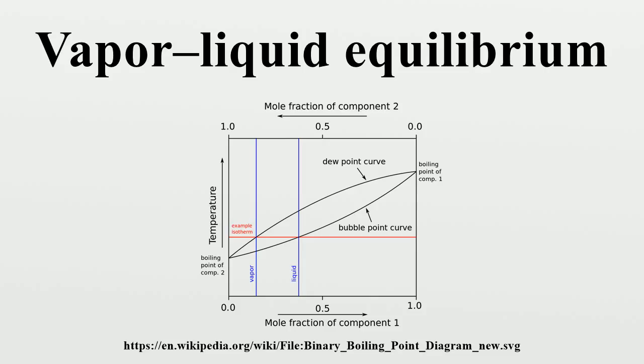If a vapor with components at certain concentrations or partial pressures is in vapor-liquid equilibrium with its liquid, then the component concentrations in the liquid will be determined dependent on the vapor concentrations and on the temperature. The equilibrium concentration of each component in the liquid phase is often different from its concentration in the vapor phase, but there is a relationship. The VLE concentration data can be determined experimentally, or computed or approximated with the help of theories such as Raoult's law, Dalton's law, and Henry's law.